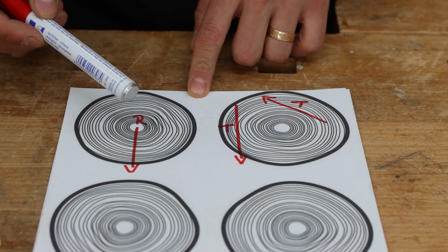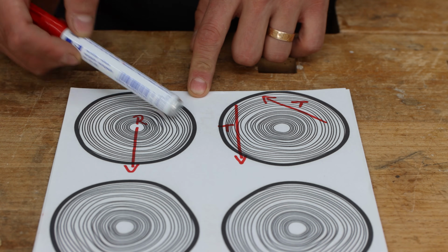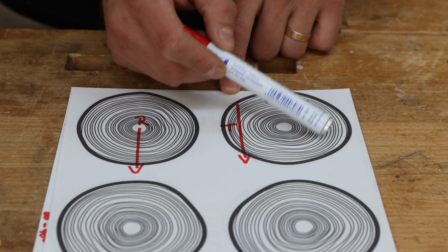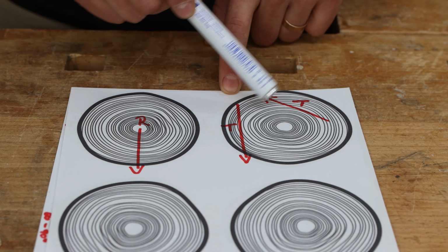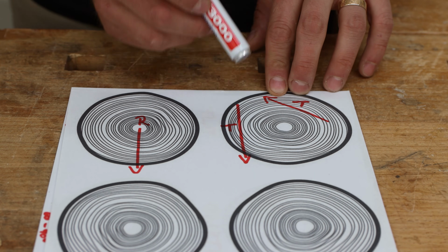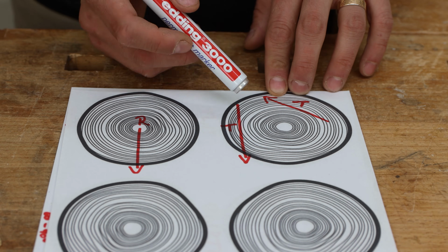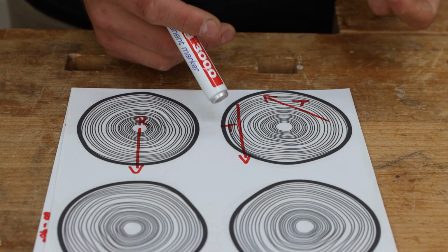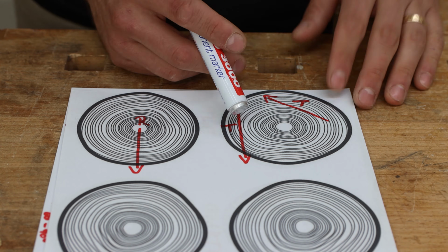Now, radial movement is across the growth rings of the tree, which means in a radial direction of the log itself. Tangential movement, however, is along the growth rings of the tree, so a tangent to the circles. Tangential movement is actually the biggest. It is about 0.27% up to 0.41% for the common wood species. Again, change in dimension per 1% change in moisture content.